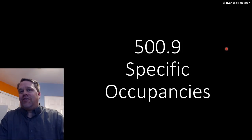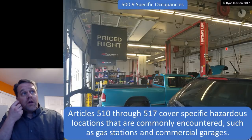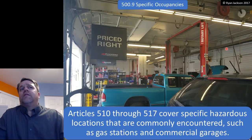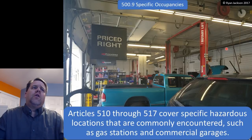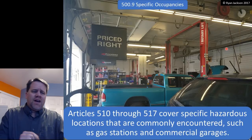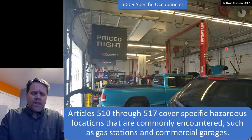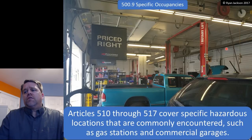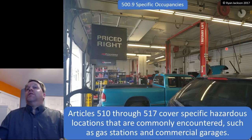The last thing is 500.9, specific occupancies. And here we just have a reminder that Articles 510 through 517 cover specific hazardous locations that are commonly encountered, like gas stations, commercial garages, things like that. Earlier I said Articles 510 through 516, and really I stand by that. Article 517 is healthcare facilities, and healthcare facilities can have flammable anesthetics, but we haven't used flammable anesthetics in the developed world for probably 50 years.